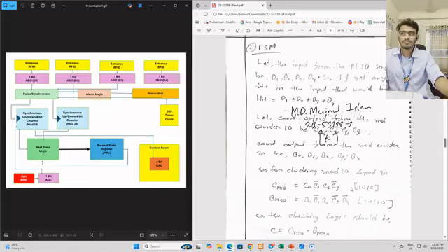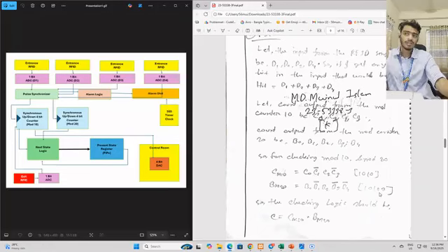I have tackled that with different things here, so I will explain it later. The binary for 10 is 1010. So I have given the expression for 1010, and 10100 is for mod 20, for 20. So this is the signal for BM20. That means if this goes high, we got the 11th signal. If this BM20 goes high, that means we got our 21st signal in the ticket counter.